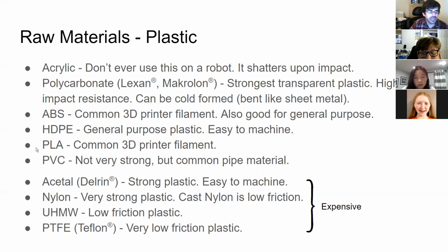So a lot of the time, we have two types of 3D printers: the hobby grade printers that print the PLA, and then we have the Markforged printer, which prints in a composite material called Onyx, which is a lot stronger than PLA. But because we know we're going to iterate parts, we want to print them in PLA first, iterate a couple times, so we know that it's good before we print them in the better but much more expensive material.